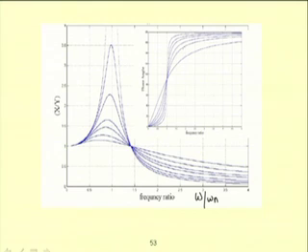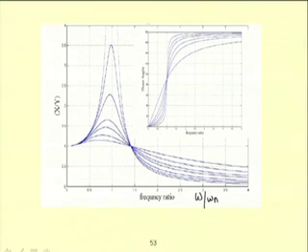Also one may observe in this case that when one operates the system at a frequency very far from the natural frequency, the phase angle phi equals 180 degrees, and irrespective of damping at omega equal to omega n, the phase difference equals pi by 2.